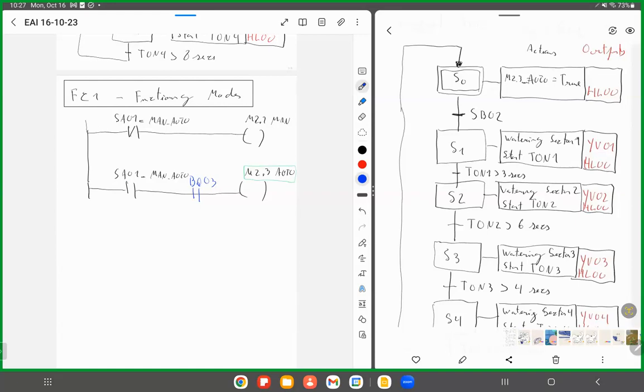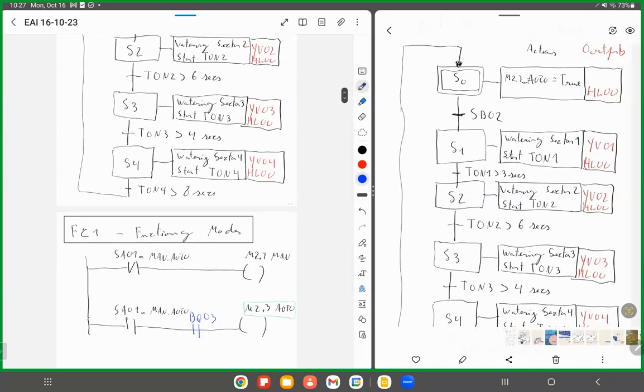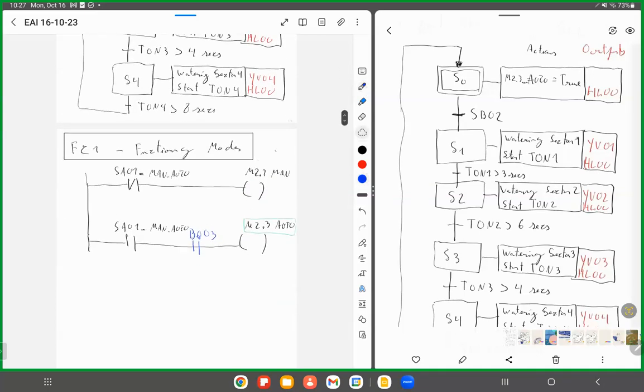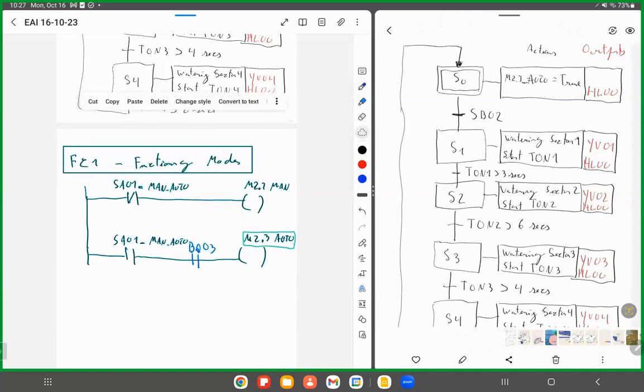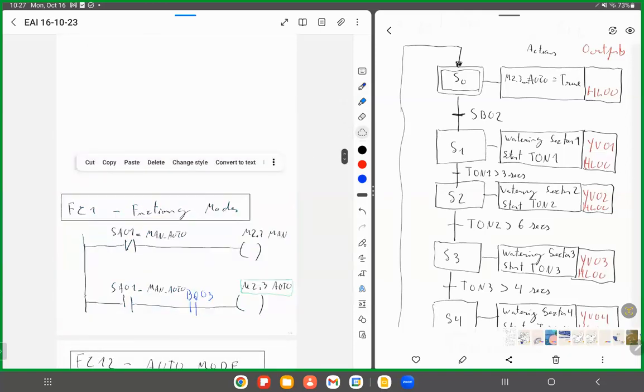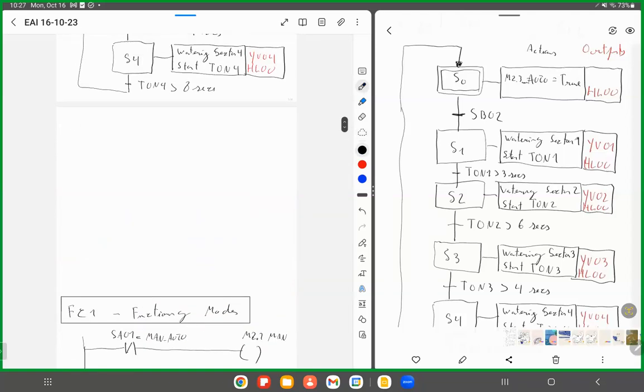Okay? Imagine that I'm using the cycle of water and the water level in the well falls below the minimum. What you are going to do in your program is going to be something like this. You have your main, OB1. I always remember OB1 as the main. This is the only function that is called automatically.